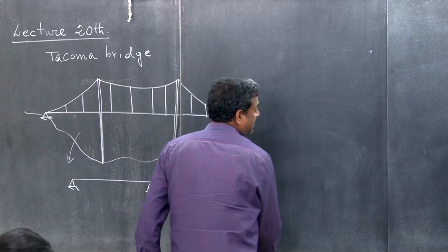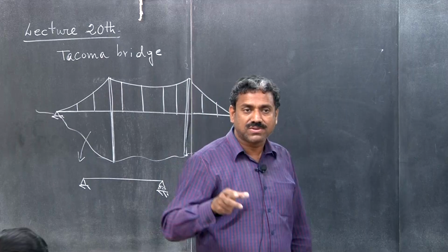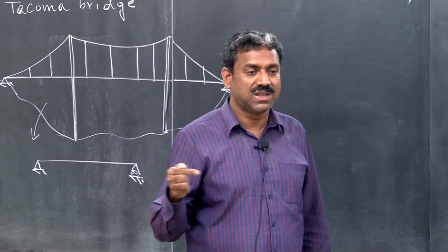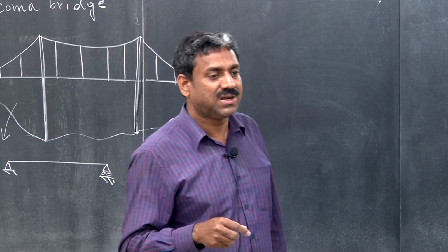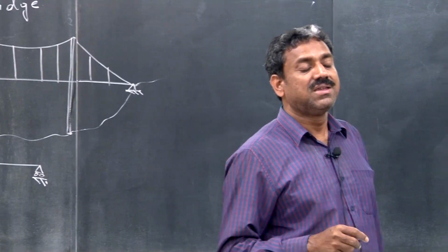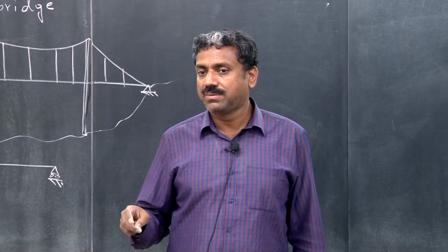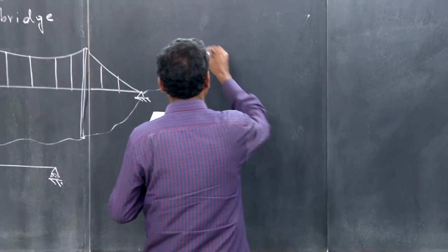I also emphasized that we have considered a 2 degree of freedom model, vertical deflection and torsion, just to keep the system low dimensional. We could have considered the lateral deflection as well, but we didn't. If we consider lateral motion, it will unnecessarily increase the dimensionality of the problem, increasing the number of flutter derivatives from 8 to 18. Then I will write the matrix equation.